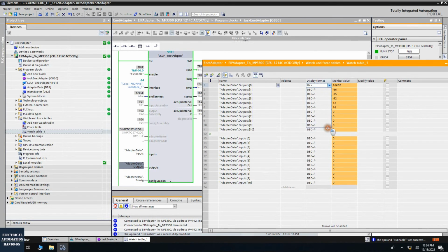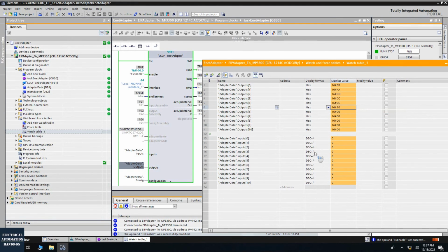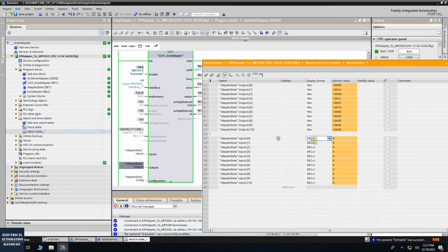So we can drag here. And if you recall, we sent AABB, and keep in mind the low and high bytes here. Because from the master side we sent AABB, but byte 0 is actually at the right side, and byte 1, the high byte, is at the left side. So you need to be careful about the low and high bytes for the word transfer. We sent AABB, CCDD, and the 0C and the 10. These are hex numbers.